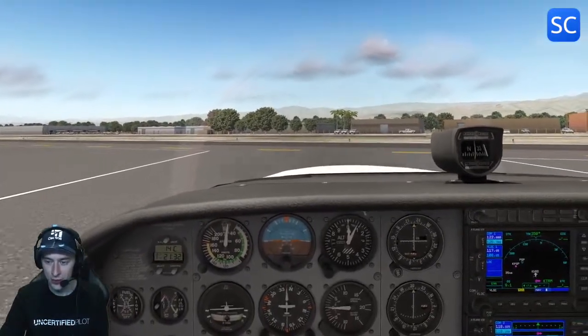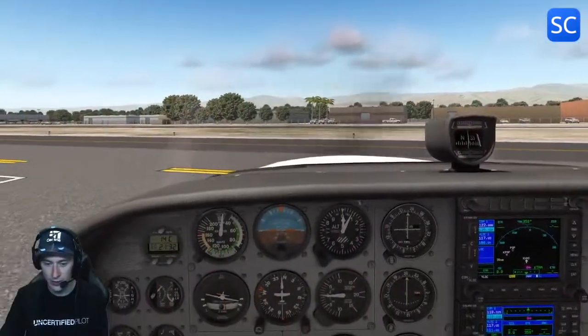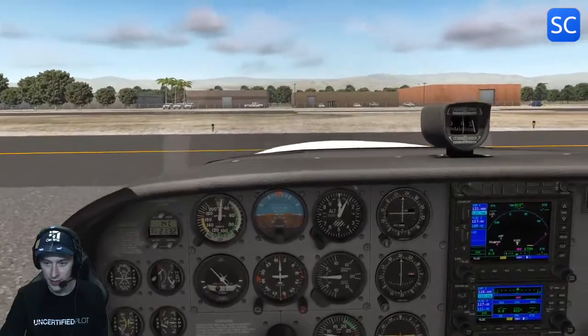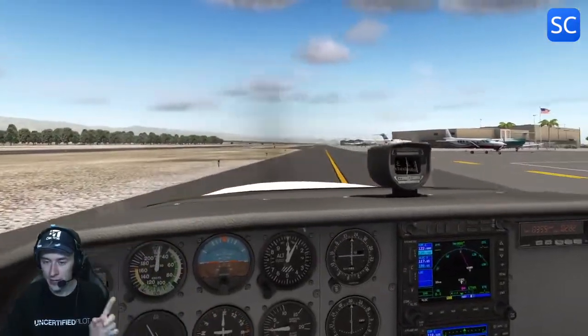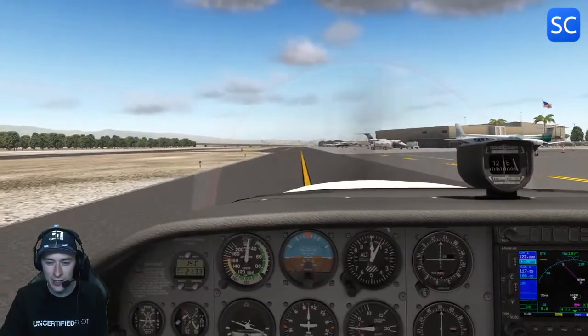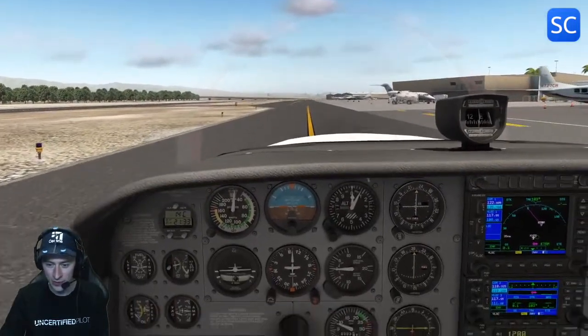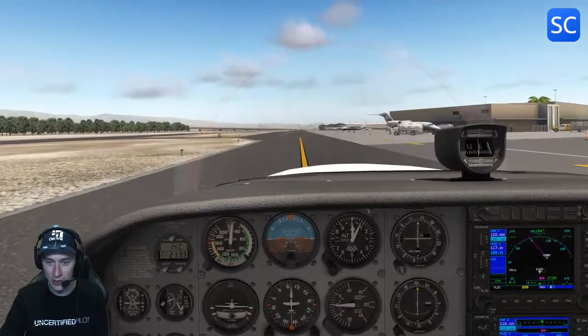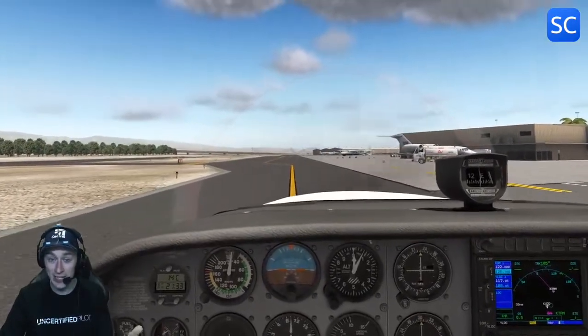Also make sure that our turn indicator and stuff is working, so let's make our turn here. Slip indicator, turn indicator, heading indicator, looks good. You can also hear, very slightly, I don't know if you guys can hear, but if I go idle, you hear that the engine is a little bit more stuttery. It doesn't burn that well, so that's why you rarely go idle on a throttle if you're doing proper engine management. All simulated in the rep.